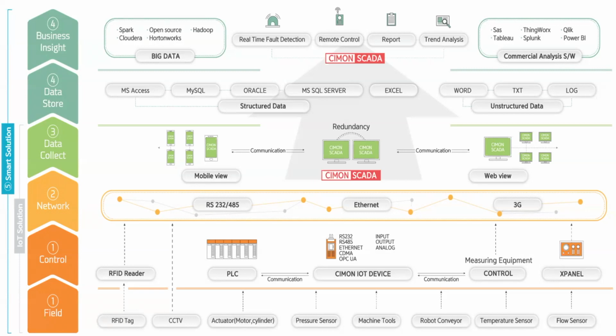Also, SCADA software is going to be running on an IPC or otherwise a normal PC, right? So it has that robust computing power that an HMI typically doesn't have. And you can also run your proprietary software and sync it to the SCADA software. It can be running with a SQL database and so forth. A lot of the time I'll get the question, what is the difference between SCADA software and HMI software? They typically look the same, but SCADA offers a wider range of features.